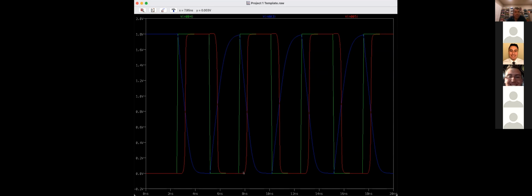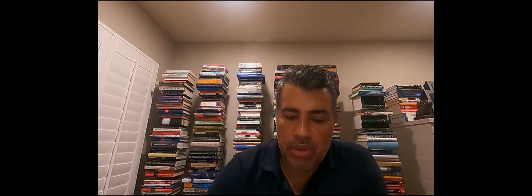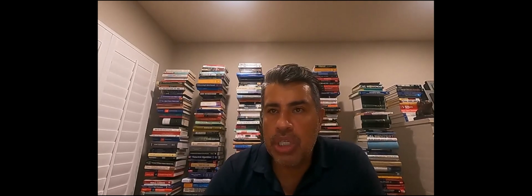Now notice still that the second inverter is cleaning up the blue, as a good logic gate should do. So it still gets good rise and fall times, because it's not loaded down. Just a hint: if you just look at the output of the second inverter, you could fool yourself into thinking everything's okay, whereas your intermediate node is really not working properly.